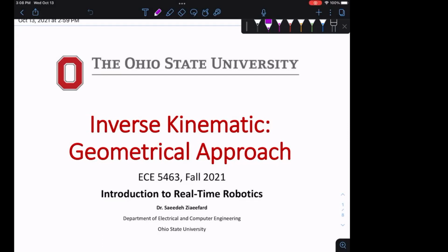What are the values of the joints in order for this end effector to reach this point? So you have to find theta 1, theta 2, theta 3. You can use the system and subfunctions that you have. Now the thing is, how many ways can I reach this point with this robot? A lot. So the problem of inverse kinematics is more complicated because there exists more than one solution.